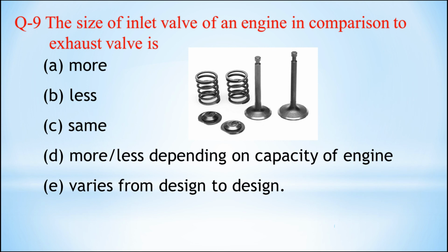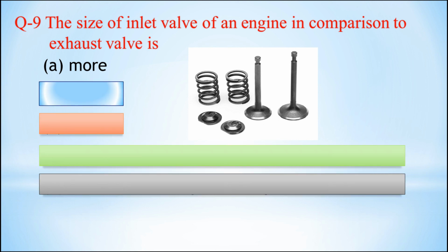Also, when we provide a smaller exhaust valve, its manufacturing cost decreases and thermal stresses are reduced. These are the reasons the exhaust valve is smaller than the inlet valve. So the right answer is option A, more.